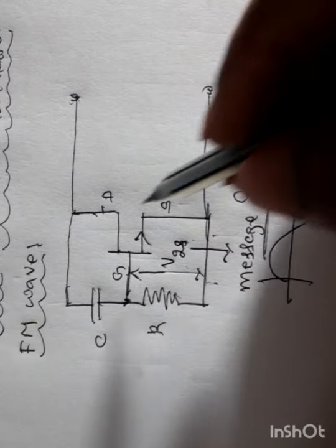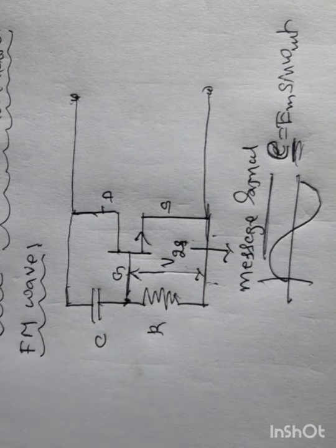Now, let us look at the total impedance. What is the difference between resistance and impedance? Both are the same. Resistance is the stopping power for the current; it resists the flow of current. Similarly, impedance means resisting the flow of current. But resistance resists the flow of both AC and DC, whereas impedance resists the flow of AC. Therefore, instead of calling it resistance, I will call it impedance, where it resists the flow of AC.